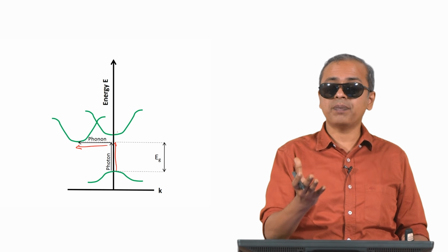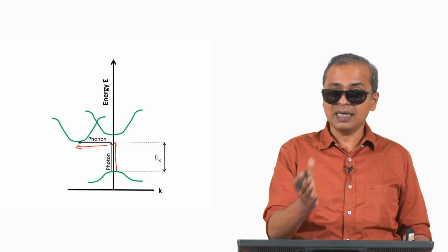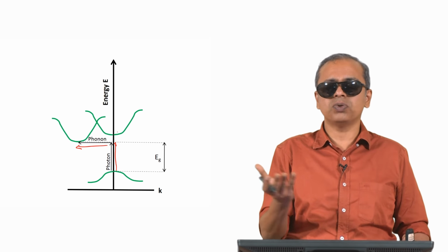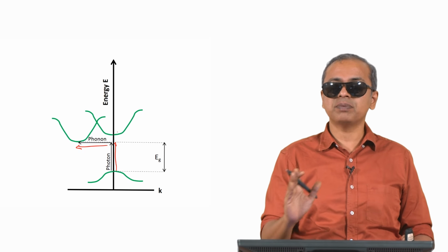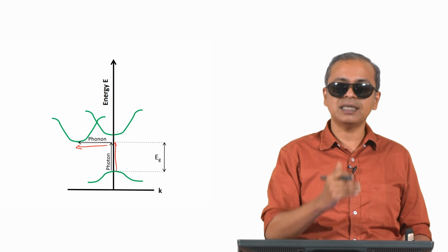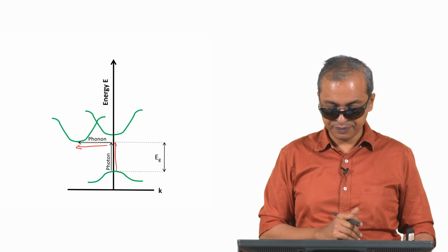And so when some other materials are explored and greater emphasis is placed on them, this is one of the reasons why that emphasis is being placed, even though you may see that band gaps do not look terribly different. But inside this there is this detail that one is direct band gap, the other is indirect band gap. So there is a better chance that it will absorb the solar radiation and do the transition, and a lesser chance in the other case.